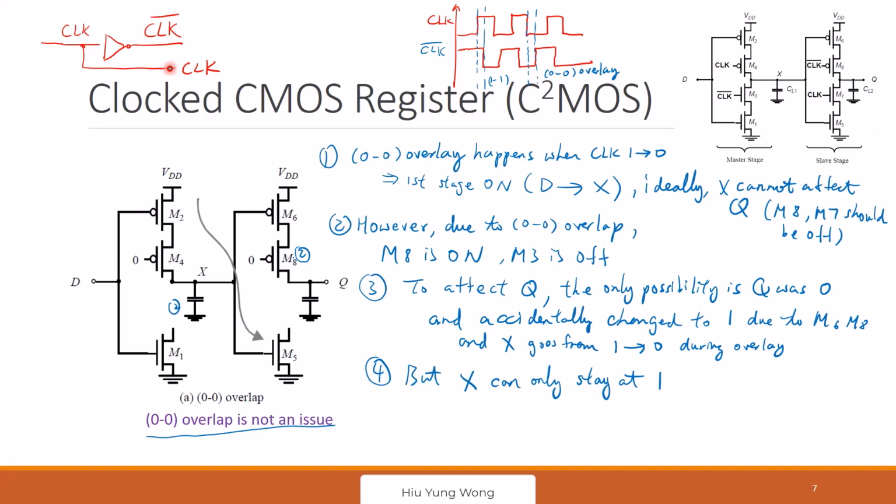Yeah, exactly. And if you want to be more specific, right? This is talking about the clock goes up. For 1-1 overlap, it is when the clock goes up, it means this one goes down. So this is TPHL. It's just the delay of your inverter, TPHL for 1-1 overlap. For 0-0 overlap, it is TPLH. Make sense? Because this is the output.